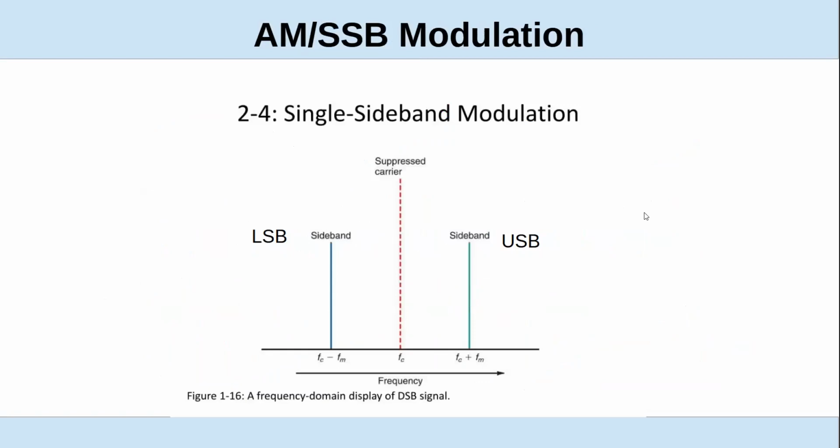In single sideband operation, it doesn't matter whether you're high or low. It's just that they're different frequencies. But the same information is there. Now there's a convention that you use lower sideband below 30 meters, and upper sideband above, unless you're doing digital, and you use upper sideband everywhere in digital mode.